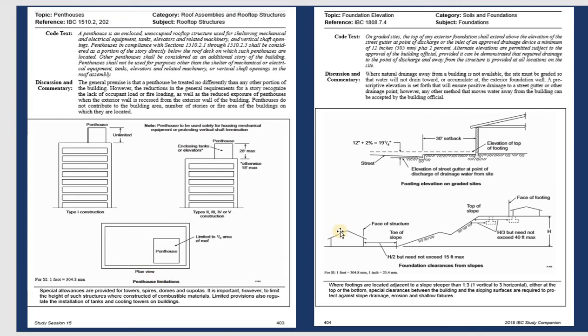And on the second picture, you can see how far the setback is if you want to do elevation from the top, from the foundation. For example, this is the house and the foundation right here. If the setback is 30 feet, right here, and it's dropped down from another level on the street, because this is the street, they allow 30 feet setback from the street.